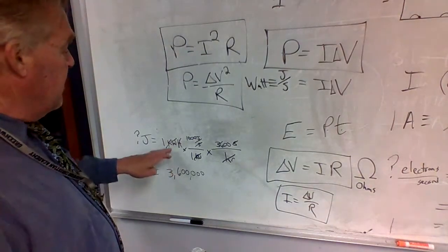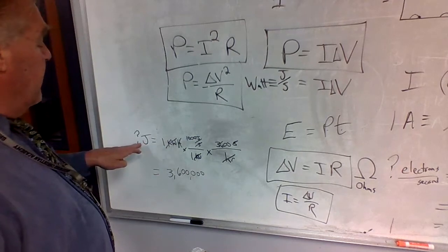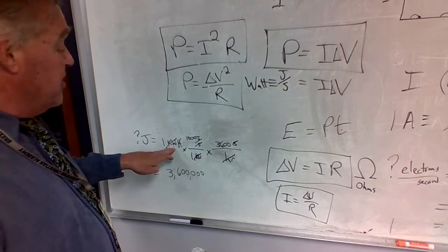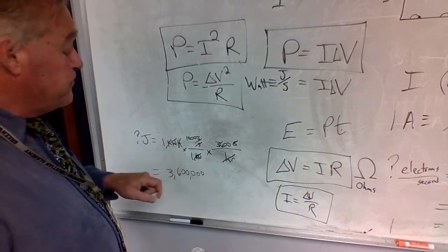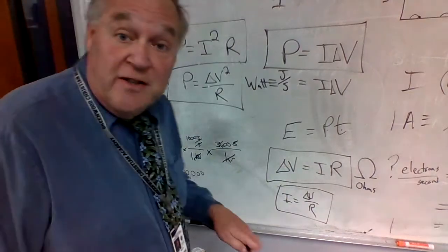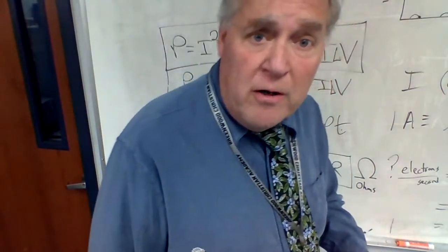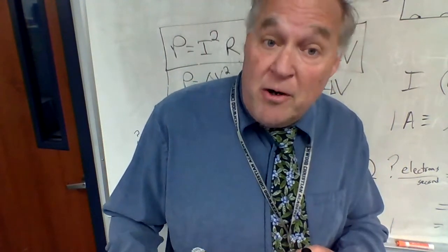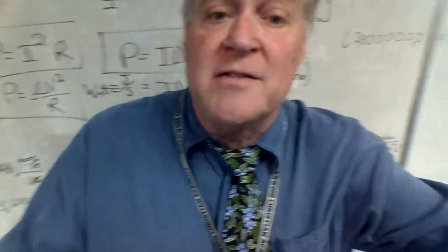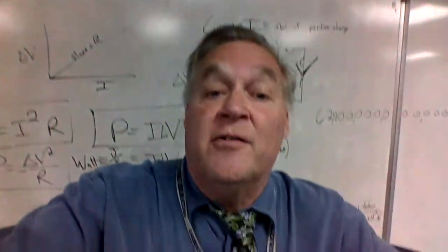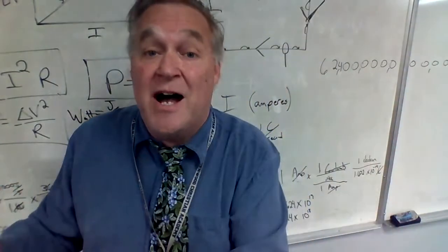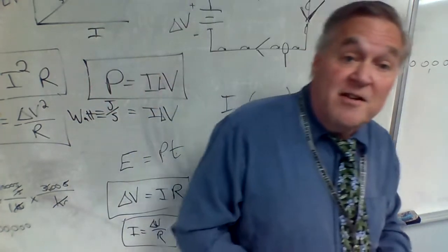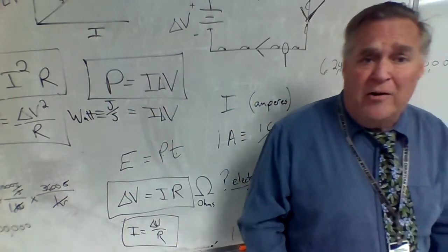Okay? So when you see the units of kilowatt hour, you know it's 3,600,000 joules of energy. This is a form of energy. It's not power. It's energy. That's a unit of energy, not a unit of power. Kilowatt hour, okay? If you're talking about kilowatts, that's a unit of power, isn't it? 1,000 watts, 1,000 joules per second, right? But a kilowatt times time is energy. So 3,600,000 joules equal 1 kilowatt hour, okay?